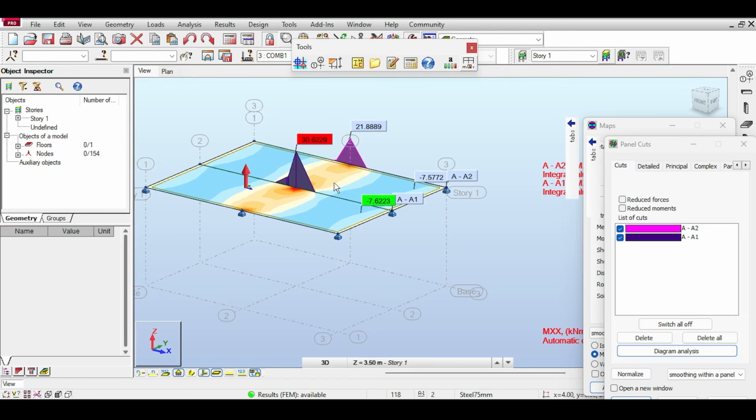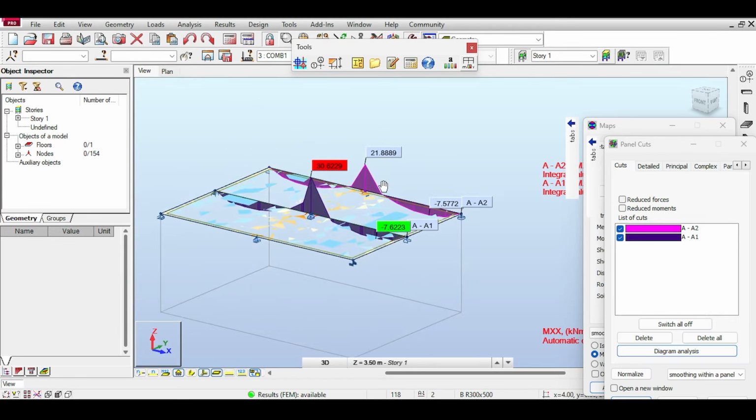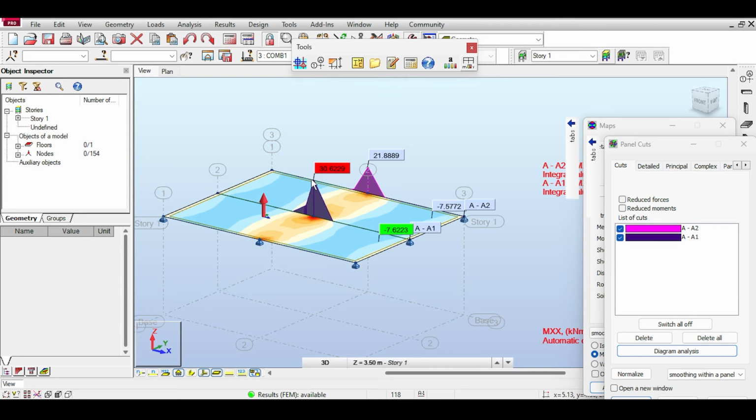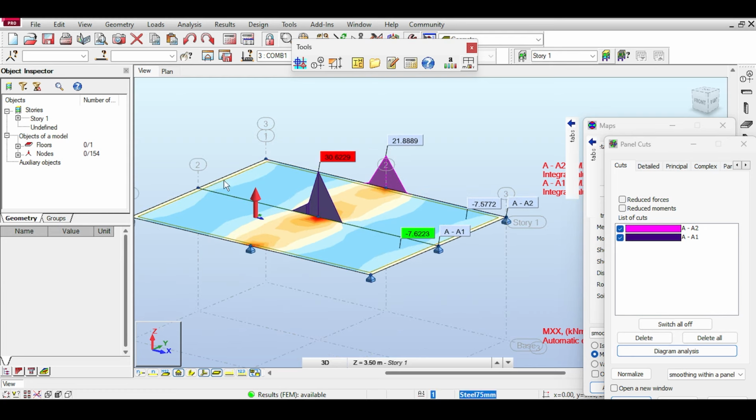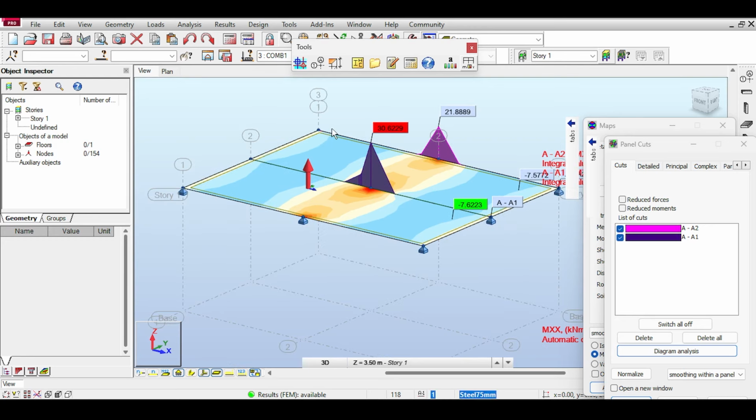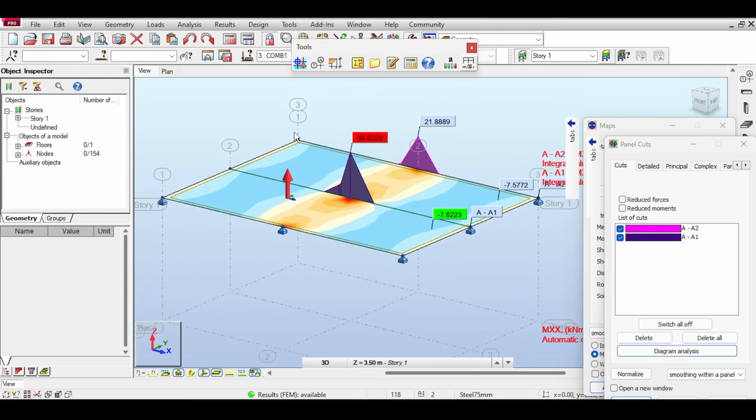And my suggestion here, because look, the AISC doesn't explicitly consider the von Mises stresses as a yield criterion. Von Mises stress is a yield criterion for multi-dimensional stress. So you could just take a 1 meter width strip and consider it like a beam and just do your calculations. It is not the cleanest version because you're missing a lot of things, but that's the version I can think of, because in the AISC code, you have a tension member, compression member, bending member for beams, but plates are seldom talked about. If you know a code chapter that talks about this, please tell me in the comment section and I would gladly make a video about it.